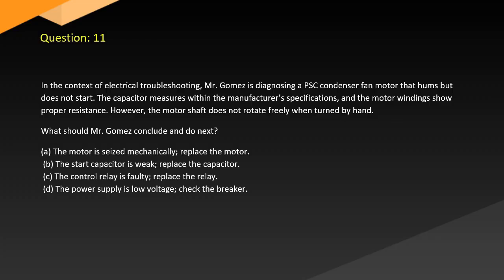Question 11. In the context of electrical troubleshooting, Mr. Gomez is diagnosing a condenser fan motor that hums but does not start. The capacitor measures within the manufacturer's specifications and the motor windings show proper resistance. However, the motor shaft does not rotate freely when turned by hand. What should Mr. Gomez conclude and do next?